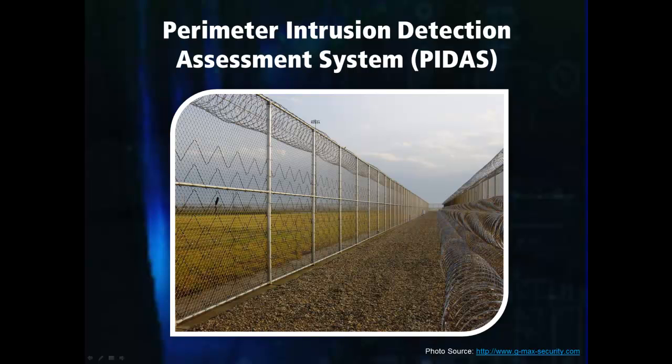Care must be taken with the design of a PIDAS to ensure it does not open up any vulnerabilities. For example, if the two fences are too close together, an adversary may be able to bypass all of the detection means in the clear zone using a ladder.